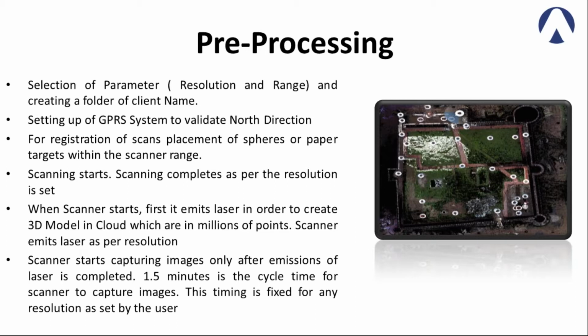For pre-processing, we have to select the parameters, resolution and range, and create a folder of client name. In the laser scanner, this is the option which you need to put. Then you have to set up a GPS system to validate north direction. DGPS points will also help.